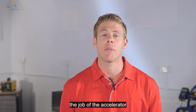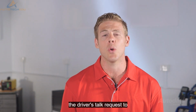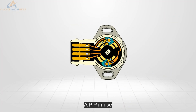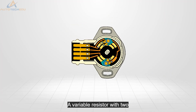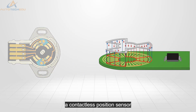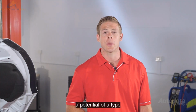Again, the job of the accelerator pedal position sensor, or APP, is to convey the driver's torque request to the ECM. There are different types of APP in use in current motor vehicles: a variable resistor with 2 position sensors for redundancy, or a contactless position sensor. Let's take a quick look at a potentiometer type APP sensor.